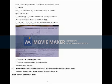Then next is entrainment. What is entrainment? Entrainment is the amount of liquid which is going along with the gas. This formula is psi is equal to E by Lm plus E. Everything is written here. Lm is the liquid flow rate in moles per second. Here you have to be careful. This is in gram mole, whereas the liquid flow rate available is in kilogram mole. So you have to multiply by 1000 to get gram moles per second.